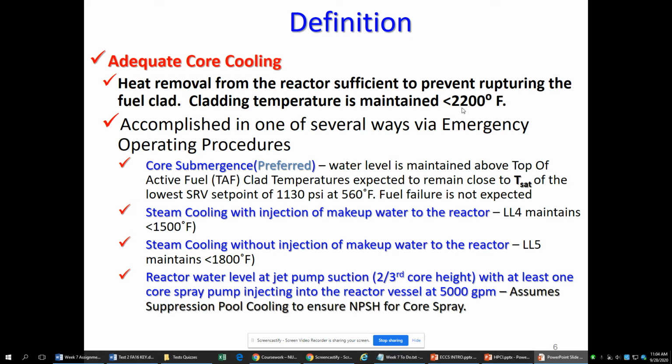won't have an explosion. Fukushima let their fuel get too hot, and once it goes above this number, you start to build up hydrogen. And if you decide to try to vent that hydrogen or get rid of it somehow, it is going to explode as soon as it sees oxygen.